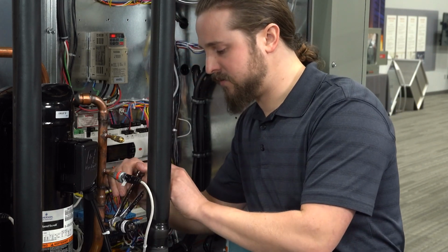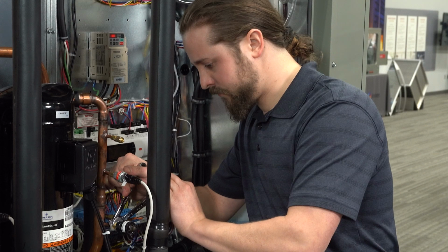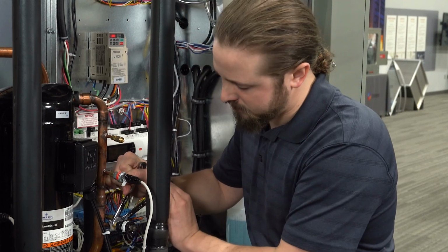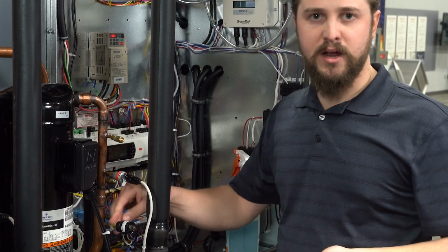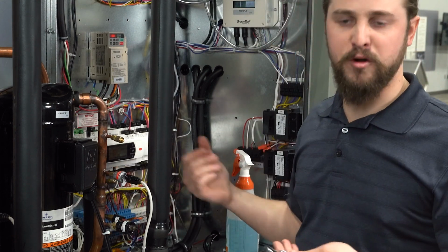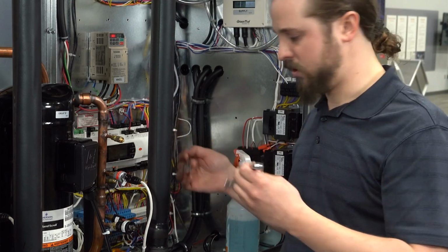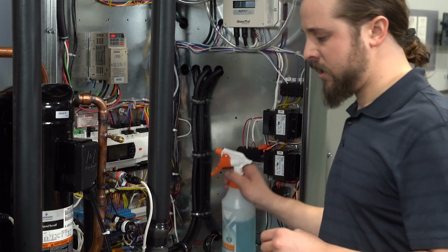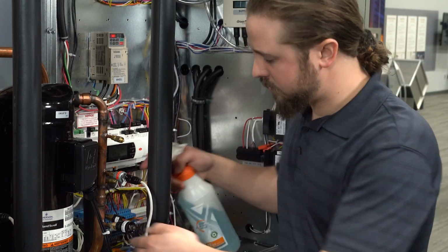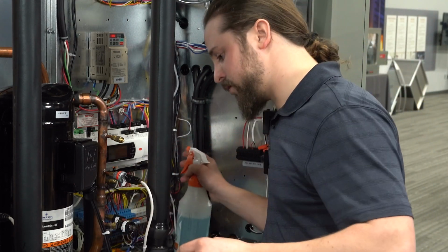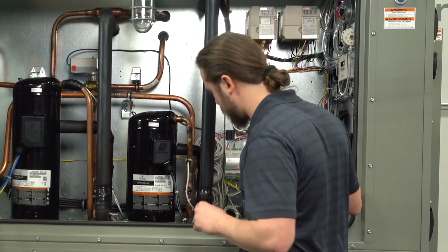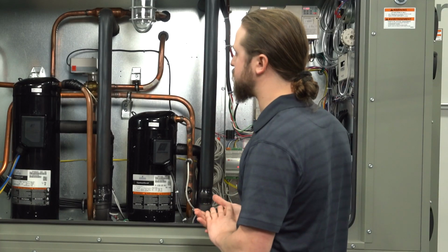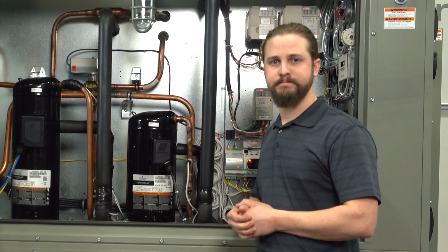So we'll do that. We'll give this a snug. It doesn't have to be very tight. You just want to look for snug. The torque spec on these is 10 foot-pounds, but honestly you can just snug it up. After you have that done, you give this another spray and make sure you're done. That looks like that's the only leak in this compartment. Good to go.